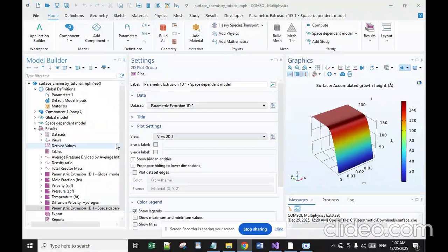Surface chemistry is often the most important and most overlooked aspect of reacting fluid modeling. Surface rate expressions can be hard to find or not even exist at all. Often it is preferable to use sticking coefficients to describe surface reactions because they can be estimated intuitively.